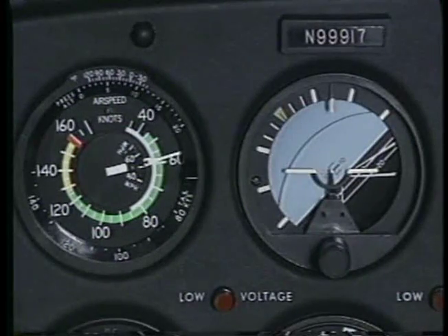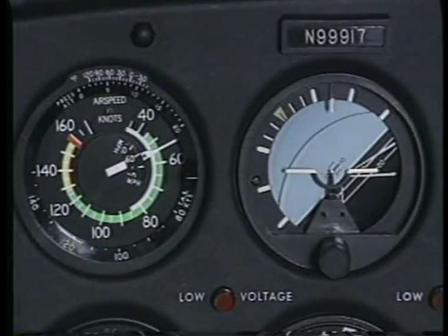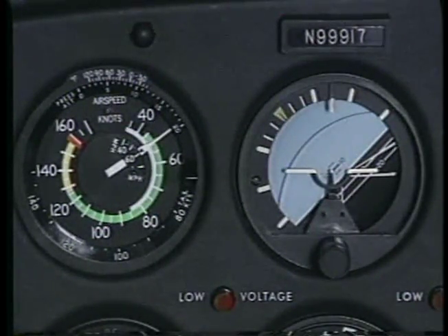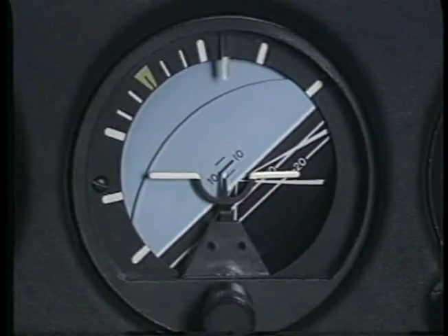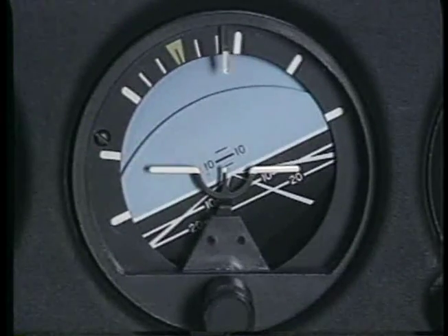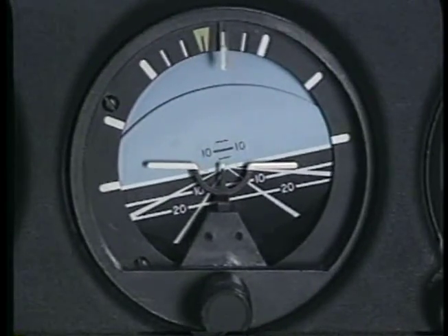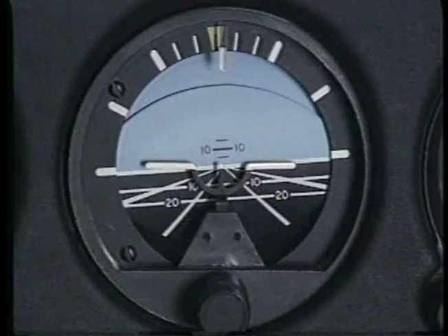When you're instructed to take the controls, you need to evaluate the situation immediately and make a proper recovery. For example, the approach to a climbing stall is signified by a high-pitch attitude and decreasing airspeed. This situation requires you to lower the nose toward level flight while immediately adding full power and leveling the wings.